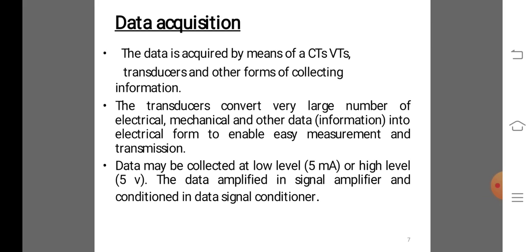Information gathered by the RTU and communicated to the ECC includes both analog information and status indicators. Analog information includes, for example, frequency, voltage, current, and reactive power flows. Status indicators include alarm signals and whether switches and circuit breakers are open or closed. Such information is provided to the ECC through a periodic scan of all RTUs. A 2-second scan cycle is typical.